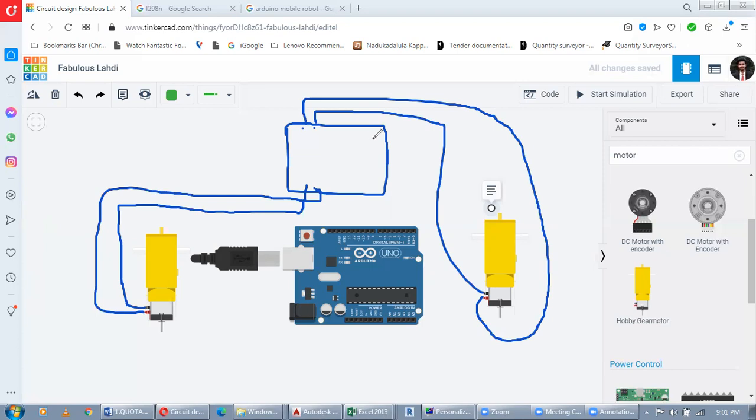So you have in one, in two, in three, in four pins, and also we have this pin and this pin, this one and this one. So we have to short circuit this one. We have to connect these two things together, these two things together. That means the motors will be running at their maximum speed, right? So then we have to obtain the second pin and connect to in one, third pin and connect to in two, fourth pin connect to in three, fifth pin connect to in four, right? So this is how you wire. These are the simple things.